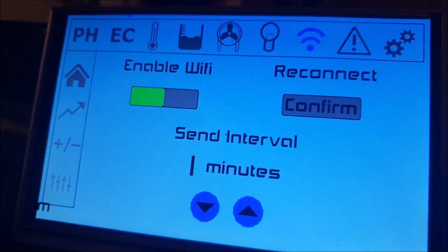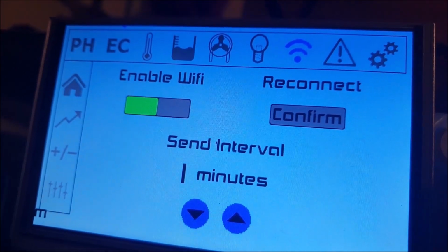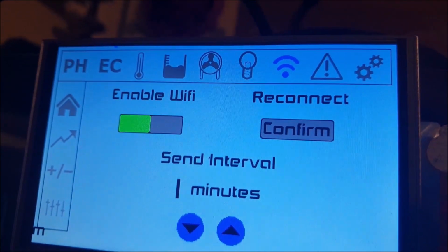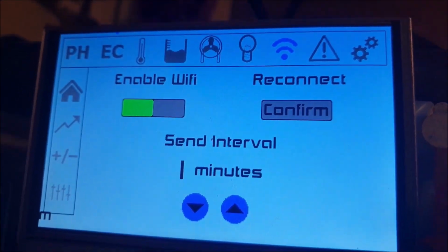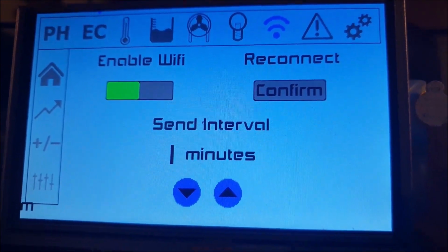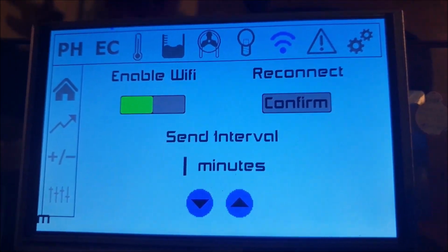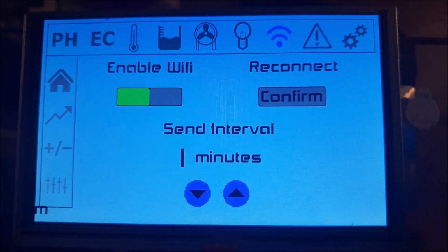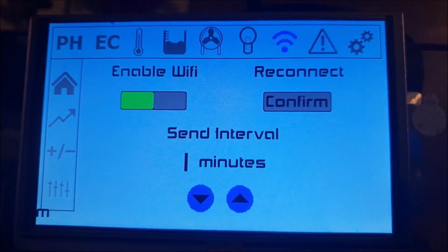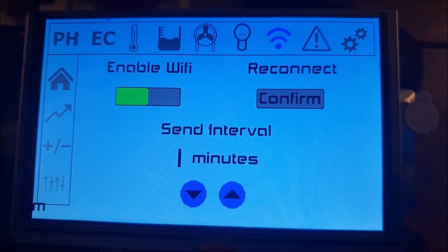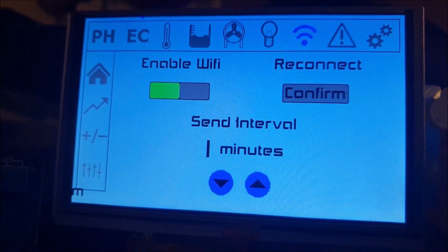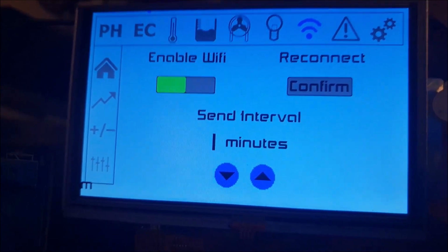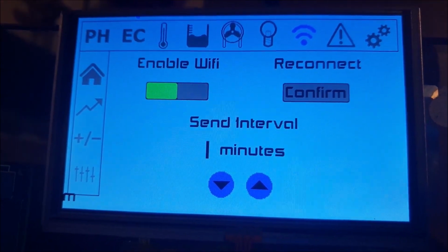So if the current value is 5 for the pH and it's dosing, it will save that value in the array very cleverly. It does a calculation based on the current value minus precision and other such things. It's literally a few lines of code, no for loops or anything like that. It would take that value and place it exactly in the array, respective of the value within 0.1.